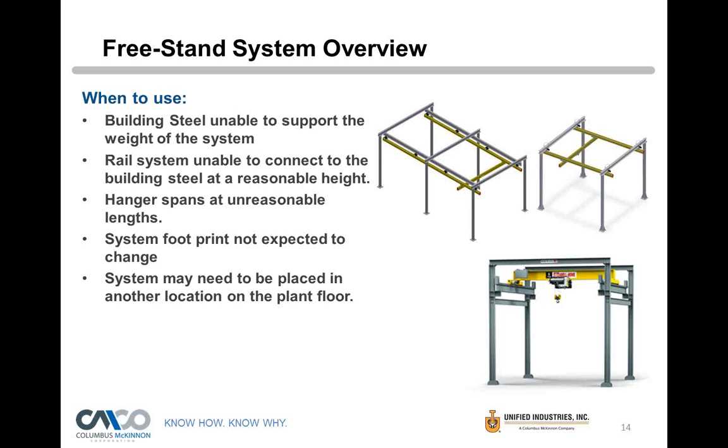I assume most people know what those are, but if you don't, the wedge anchor would be almost like a wall anchor that you see in drywall where you'd screw it in the ground, and then when you tighten it, there's two side pieces that wedge it into the ground. The adhesive anchor, you drill a hole again, but you put in a liquid adhesive, like a concrete adhesive, put the screw in, bolt it down, and then it hardens, and then it's permanently in the ground. Okay, thank you.